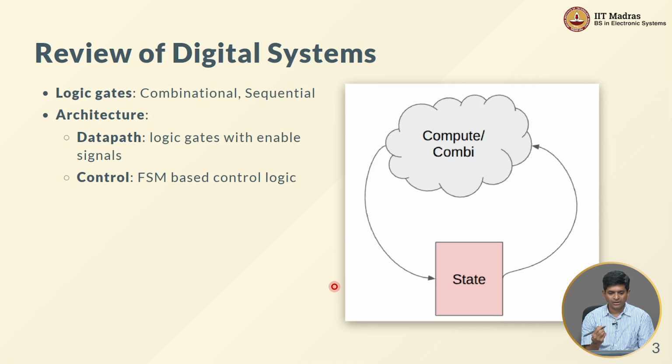In general, we have different kinds of logic gates that we use when we are constructing digital systems. Broadly, they are classified as combinational. The idea of combinational being that I give it a certain set of inputs and the output is completely dependent only on the present set of inputs. AND gates, inverters and so on are examples of combinational logic. So is the lookup table present inside every FPGA. The lookup tables that are used to build up the FPGA logic are also combinational gates which can be programmed to act as any kind of arbitrary Boolean function, by directly encoding the truth table into it.